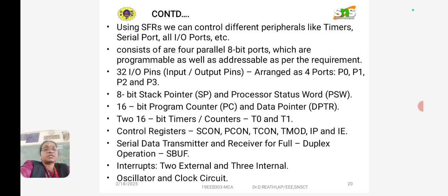It also consists of 4 parallel 8-bit ports which are programmable as well as addressable as per the requirement. So there are 32 IO pins arranged as 4 ports, P0, P1, P2 and P3. It also consists of an 8-bit stack pointer and the processor status word or program status word, PSW, a 16-bit program counter and a data pointer. Along with this, it has two 16-bit timers/counters, T0 and T1.